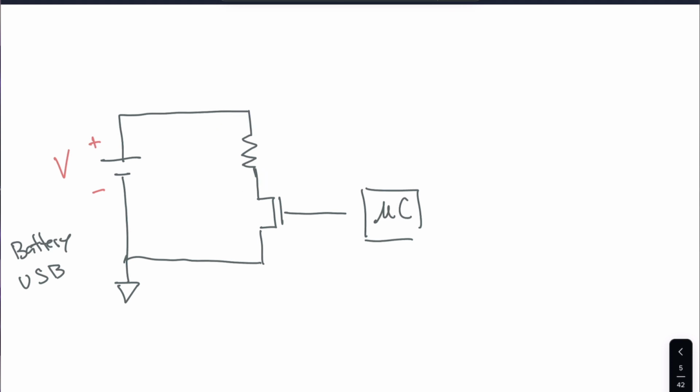This here is the symbol for a resistor. And you might see that have a quantity, something like, I don't know, 330 ohms. When you have a resistor and voltage, that means the voltage is going to be pushing current through the resistor, assuming the circuit is actually closed. So you'll have a current, and we usually indicate the current as going from the positive sign, wrapping around back to the negative sign. That's the flow of current. It's actually the opposite flow of electrons, but that's the flow of current.